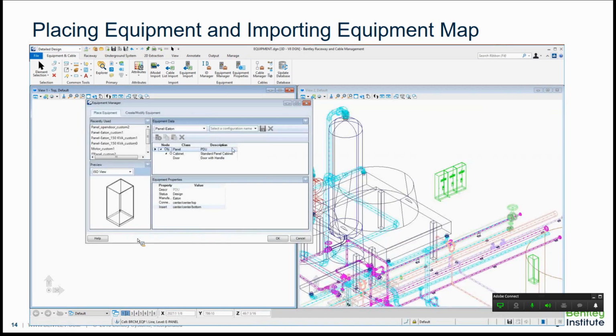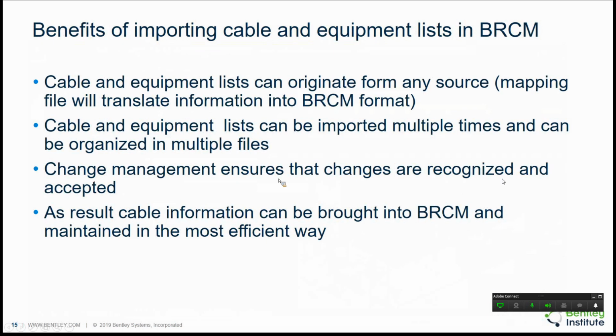Okay, so in the next step, I just want to briefly review the benefits of importing cable list and equipment. You don't have to format your cable list in a specific format. Whatever format you currently have, you can customize Bentley Raceway cable management to work with that. If they come in from different applications or if they're manually created, that's perfectly fine. This can be brought into cable management effectively.